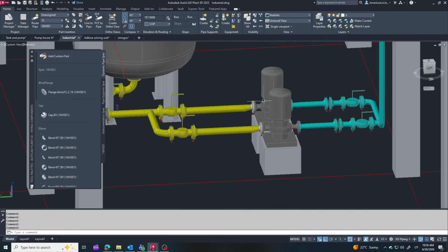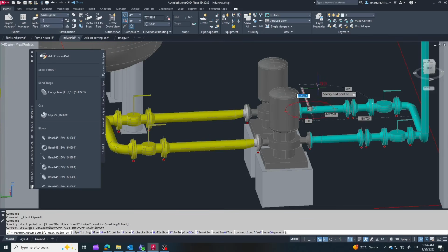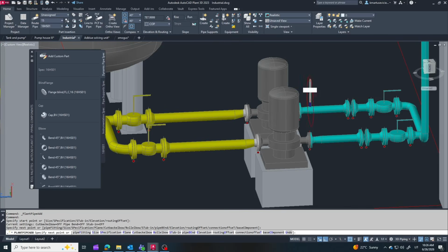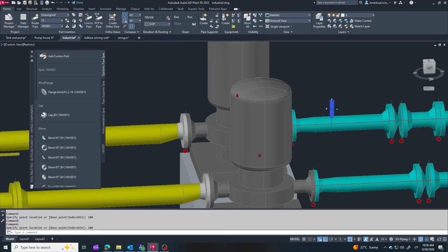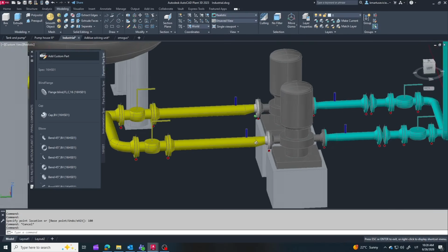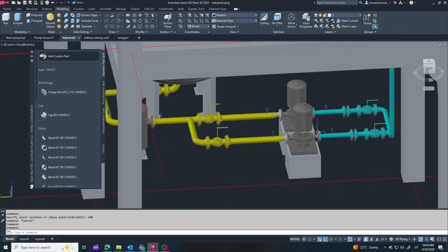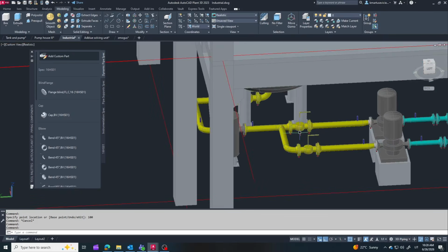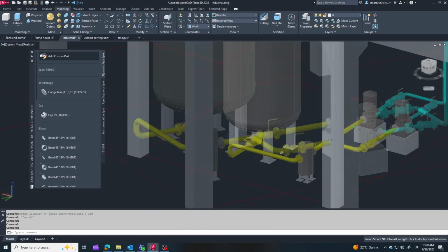Pumps are also commonly equipped with pressure gauges. A pressure gauge on the suction side shows the inlet pressure, while the gauge on the discharge side shows the outlet pressure. By comparing these readings, operators can quickly determine whether the pump is operating normally or if there are problems such as a clogged strainer, low suction pressure, or excessive pressure losses in the system. They are simple instruments, but they provide valuable information during both operation and troubleshooting.